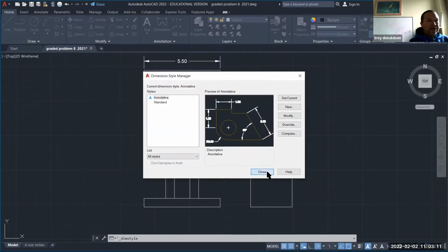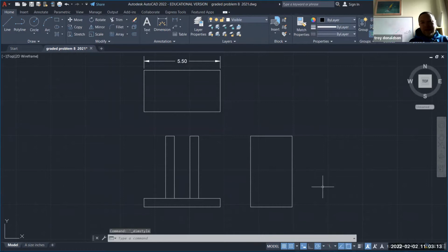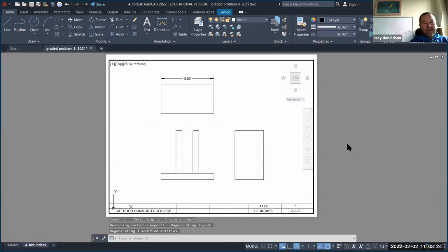All right. So that kind of gets you many things going, some dimensioning, some drawing techniques, and some paper space model space stuff. So get a title block going. You can get some layers going also, and start to organize things onto layers.